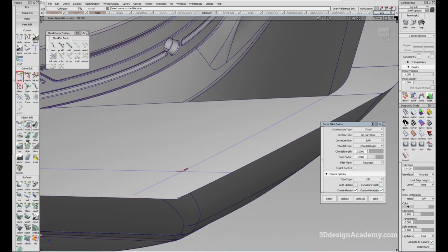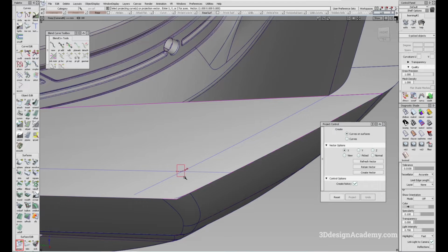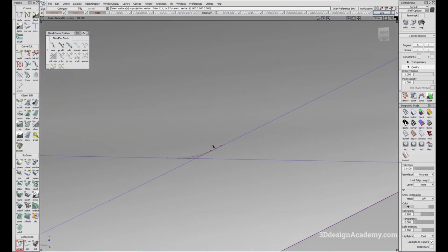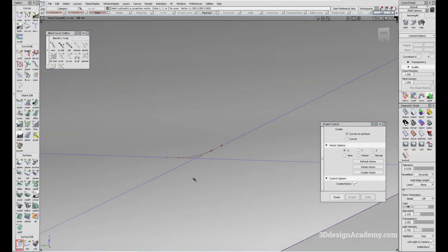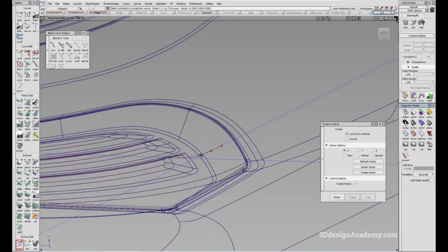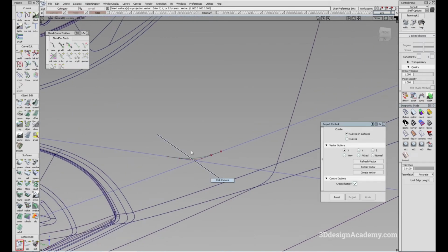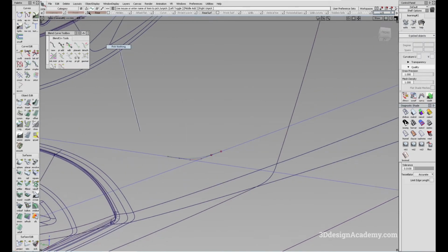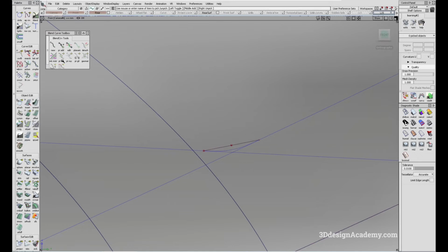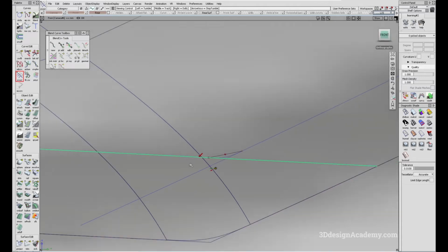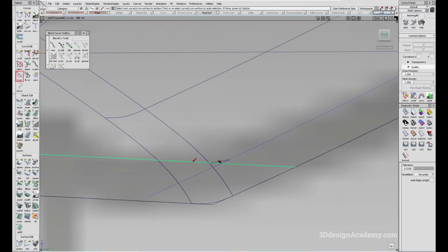And what I'm going to do is I'm just going to project this. Now the problem is, because the curved surface is merged on either side, I'm going to just delete the curve. Oh, actually, before I do that, let me just strike a curve from here to here like this. And using the curve section tool, I'm just going to trim these pieces over here. So, oh, wrong side. So let me just do Control Z. I'm going to pick this side, and what? Why is it doing that?